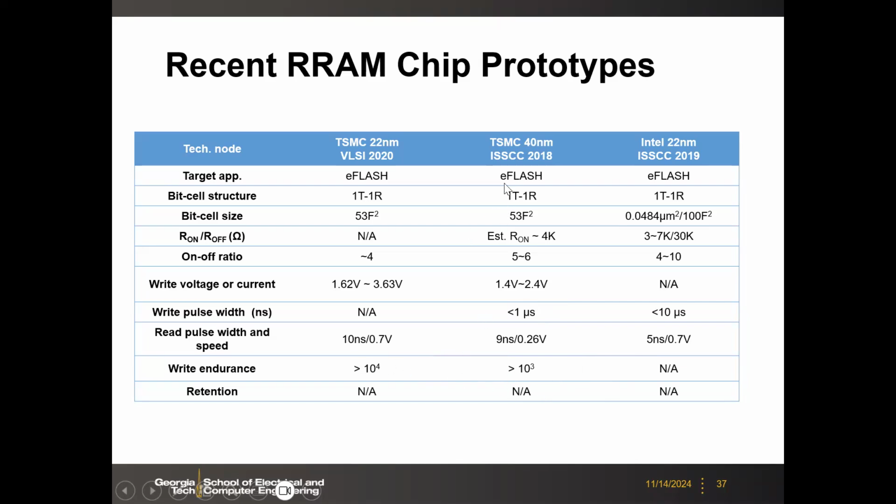So for this particular eFlash application, it is good enough, because the embedded flash is a floating gate transistor with the logic. I'm not talking about the NAND, the separate one. I'm talking about embedded flash. The latest technology you can have is 28 nanometer. Below 28 nanometer, industry thinks it's impossible, because of the increased mask cost and the physics there.